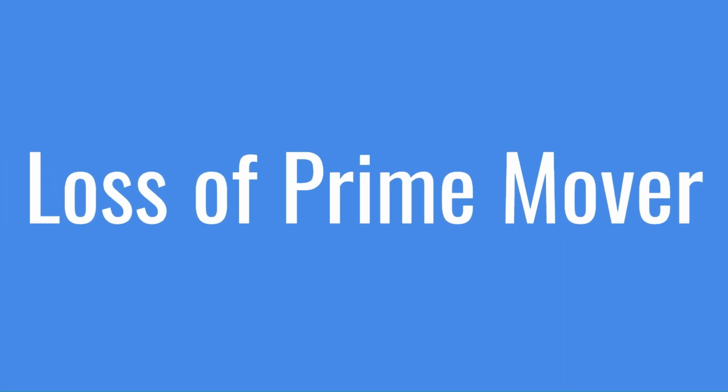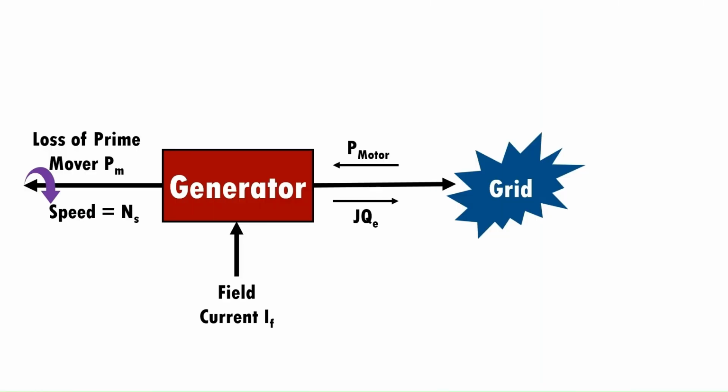In case of loss of prime mover, that is the loss of mechanical input, the machine continues to remain synchronized with the grid, running as a synchronous motor. The machine now draws a small amount of active power from the grid in order to drive the turbine and meet the losses taking place in the machine. At the same time, the machine supplies reactive power to the grid since its excitation is intact. Running in this mode is not harmful to the generator, but it is definitely harmful to the prime mover like a steam turbine.